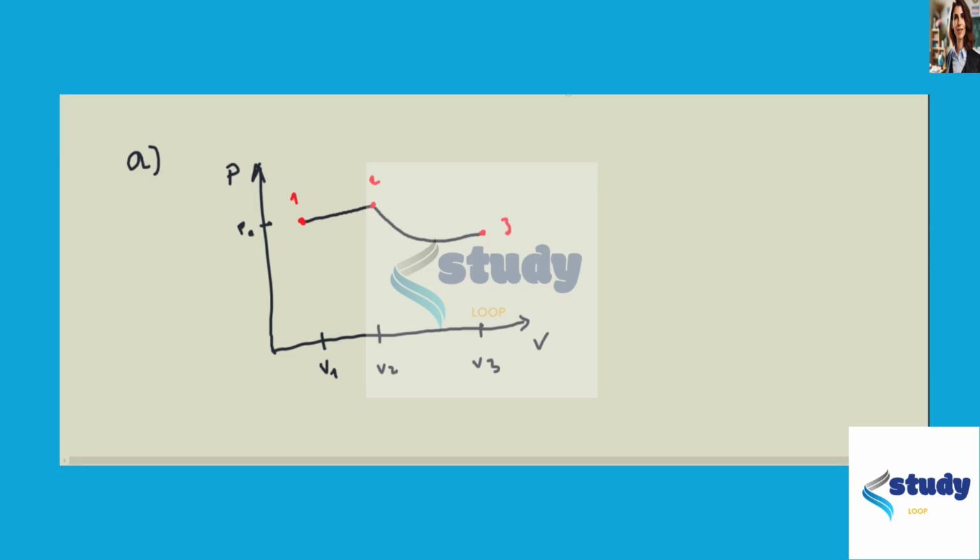And this would be the PV diagram for this sequence of the process, where the turbocharger and the intercooler are doing their work on the gas before the gas actually enters the cylinders of the engine. This is for part A of the problem.